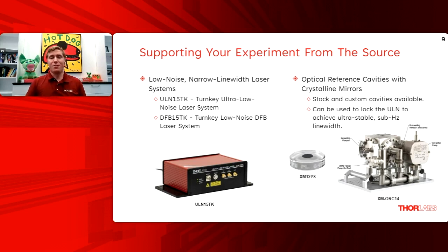The DFB, you're going to be looking at a 50 kilohertz linewidth, but you're looking at a lower price point, and another benefit of that system is that you're going to have mode hop free tuning. So in certain applications, that is going to be valuable. Kind of going back to the reference cavities, I want to make sure I mention in particular that we make the supercrystalline mirrors that get used in these. So we can do customs of them between 1 and 5 microns currently.